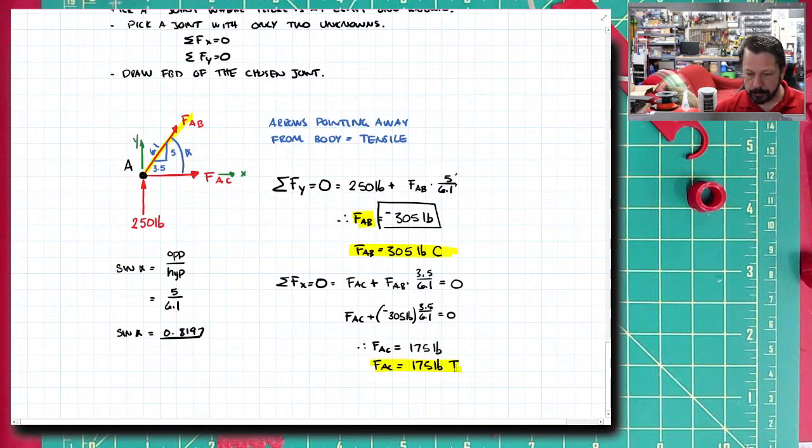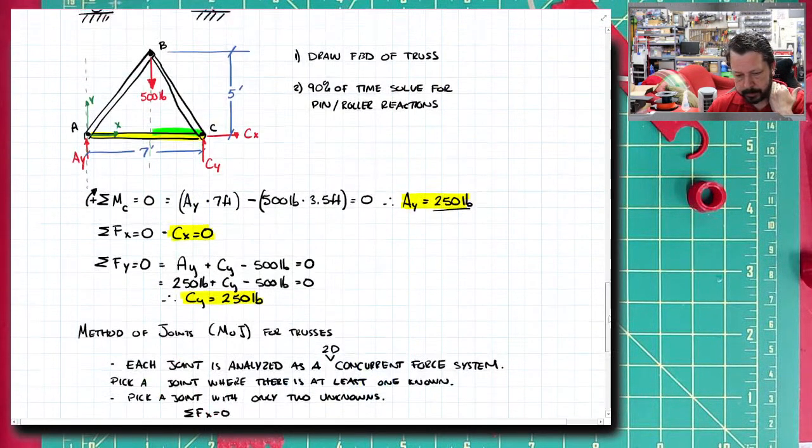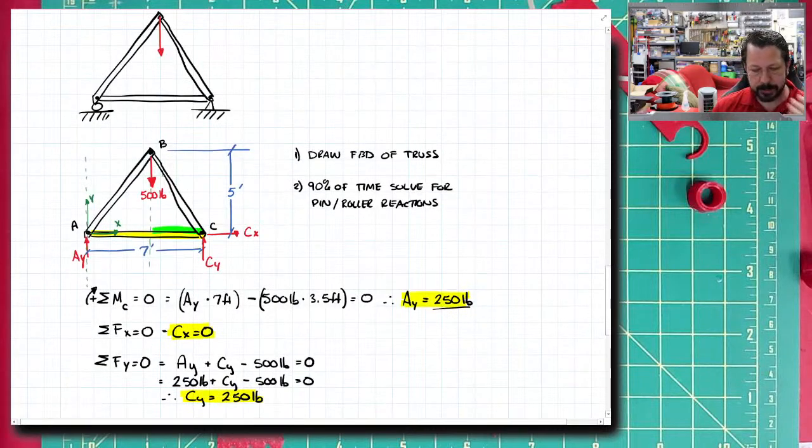All right. Now, in this particular truss, we know that by symmetry, we have symmetric geometry. We have symmetric loading. Technically, there's this CX over here that's not on A, but we decided that CX is 0. And we have symmetric external forces. So when you have that, then once you've solved half of the truss, the mirror image half is the same value. So AB and BC are the same value.